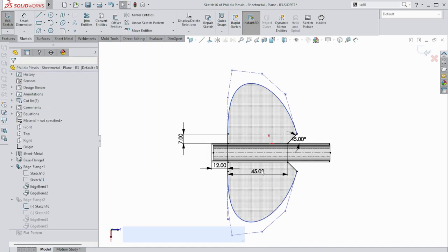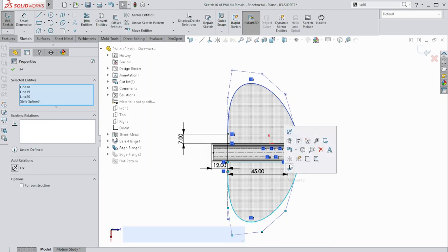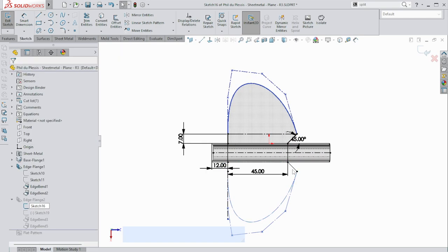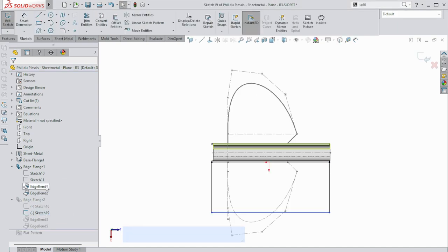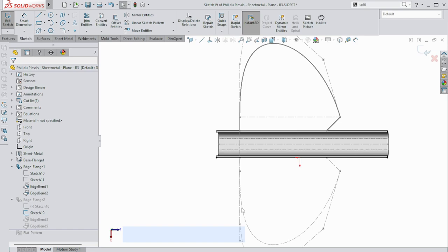If you leave it as it is, it's going to fail. What you need to do is select the sketch and make it construction geometry, because we can only have one sketch in there. So you'll see now if I go into the second sketch, the other half of the wing, and I edit the sketch, there's that sketch that I've copied across. All I have to do is delete these 3 lines and select these other 3. So that spline, these 2 straight lines, not that one. Doesn't matter. And then convert them.